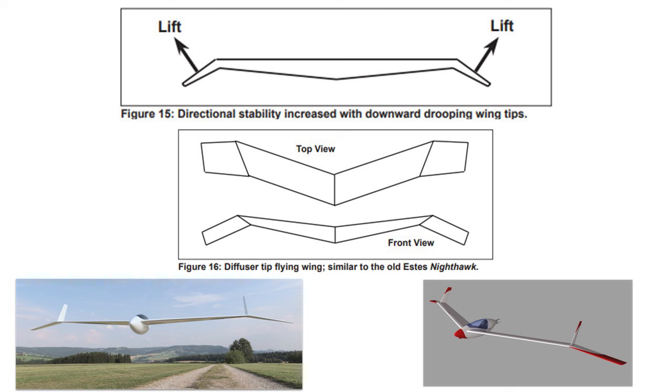Anyways, if we design the wingtips with a bit of anhedral and washout, we can simulate lower surface wingtip fins or winglets, and the directional stability will then be manifested through the outward lifts generated by the wingtips. You'll probably only ever see these on flying wings. If diffuser tips are used, we can pretty easily increase directional stability, and this helps make up for the absence of the vertical tail in the tailless aircraft. The drag that these produce also acts in a similar manner to the toe-in winglets.